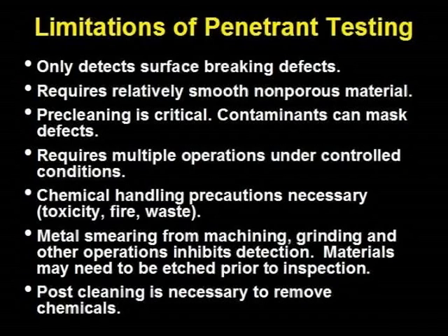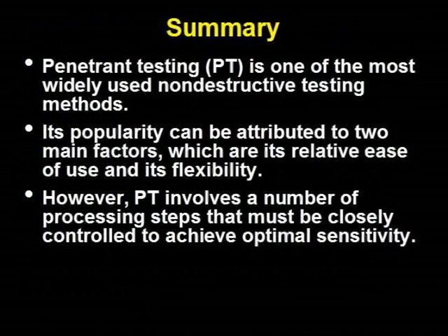Toxicity, fire, waste. Metal smearing from machining, grinding, and other operations inhibits detection. Materials may need to be etched prior to inspection. Post-cleaning is necessary to remove chemicals. In summary, penetrant testing is one of the most widely used NDT methods because it is flexible and relatively easy to use. The downside is that PT requires closely controlled processing steps to achieve optimal sensitivity.